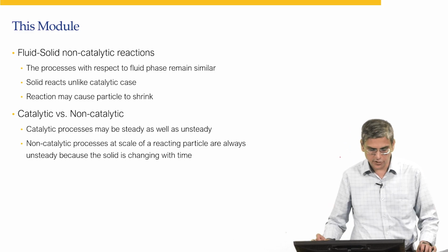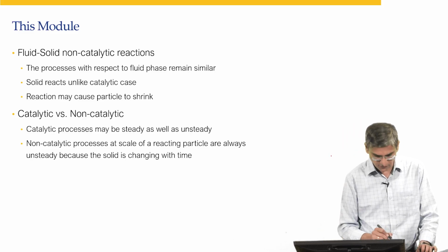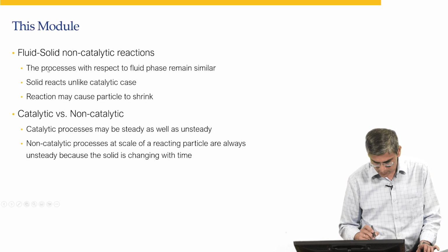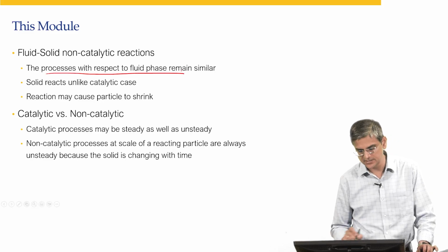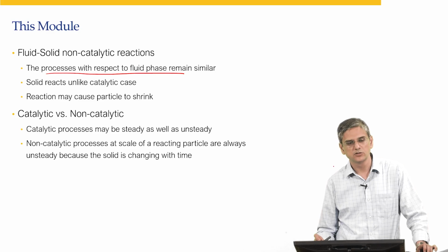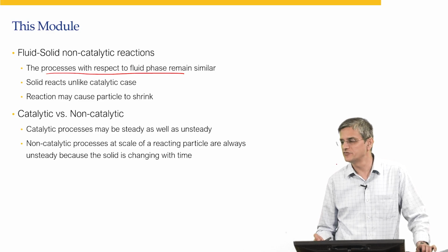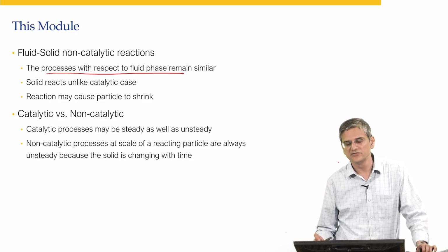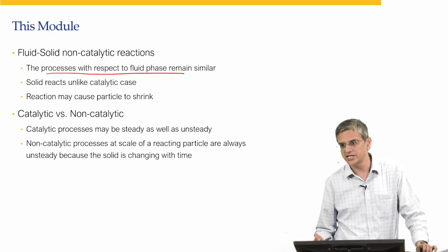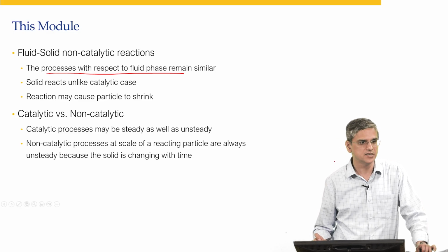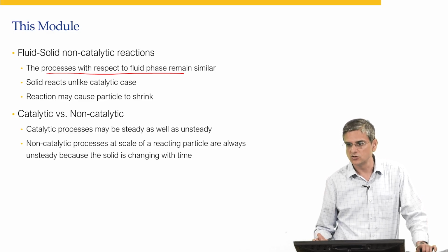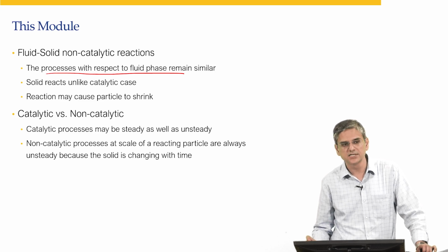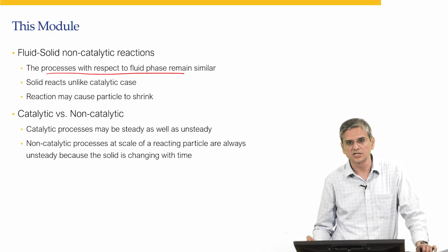In this module, we are going to look at fluid solid non-catalytic systems. The processes with respect to the fluid phase remain similar, with no change in the fluid phase. So if there is external mass transfer limitation, there would be external mass transfer limitation here also. There might be internal diffusion without any reaction taking place, as in the composite pellet I talked about briefly in the previous module, and then there is internal diffusion with reaction taking place.